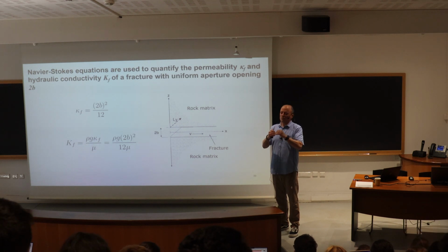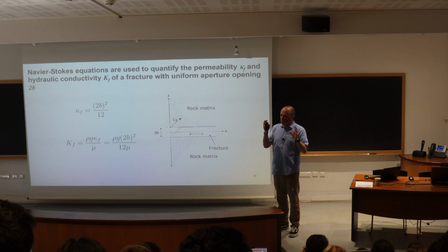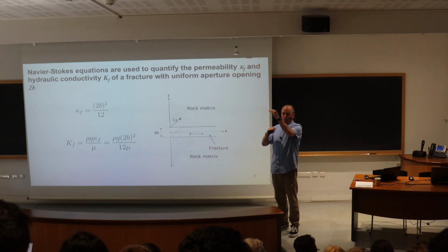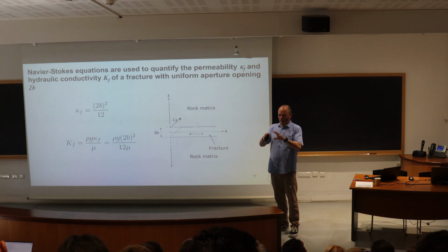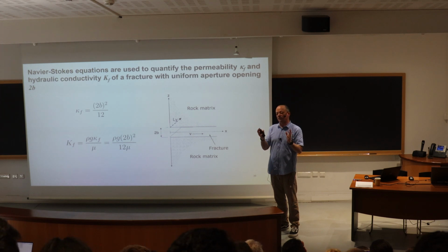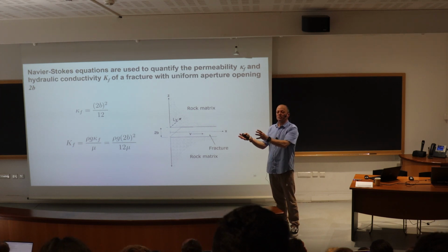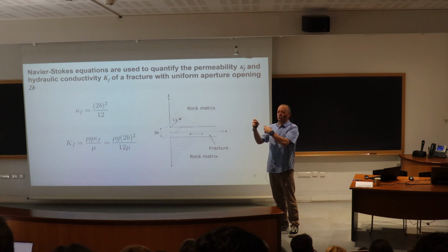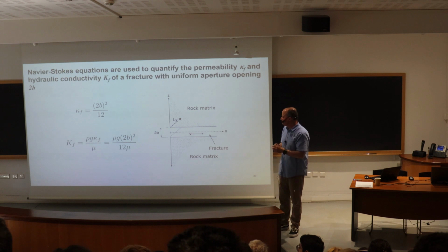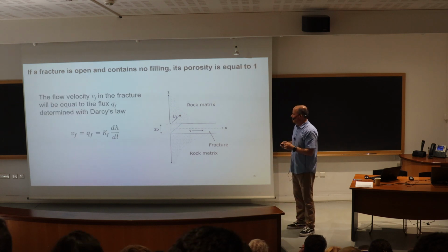Knowing the hydraulic conductivity of all these fractures, knowing the connections, basically use a Darcy approach, about the same as when I showed with the layers, where you have these distributions of hydraulic conductivity from the individual fractures, and come up with an equivalent hydraulic conductivity, and then use that at a larger scale for some applications.